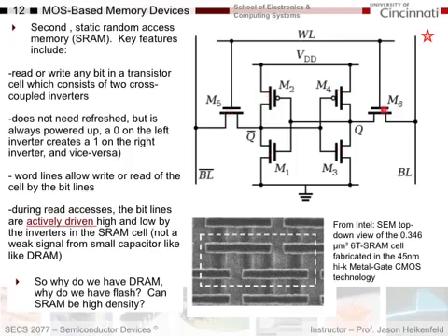The question is, can SRAM be high density or as high density as DRAM? Well, of course it can't, because for DRAM, we had 1 C, 1 T, 1 capacitor and 1 transistor. Very small. For SRAM, you've got 6 transistors. And so your density of memory you can achieve is less. And so although SRAM can be faster and doesn't have to be refreshed, you're not going to get the memory density and the maximum storage for one chip as you would have with DRAM.